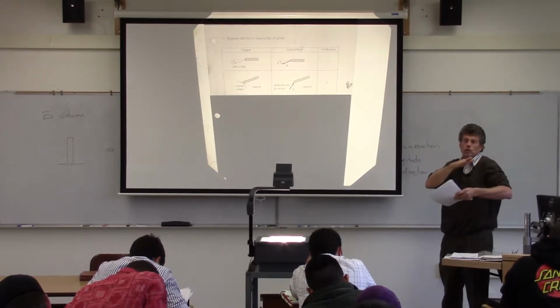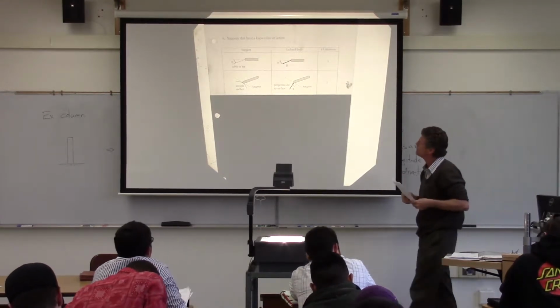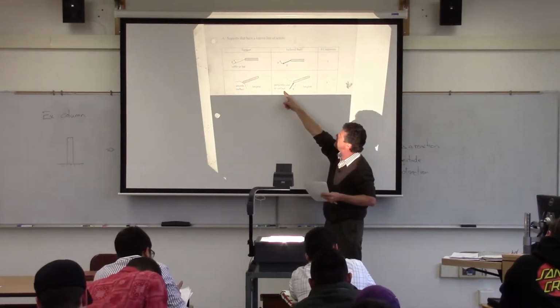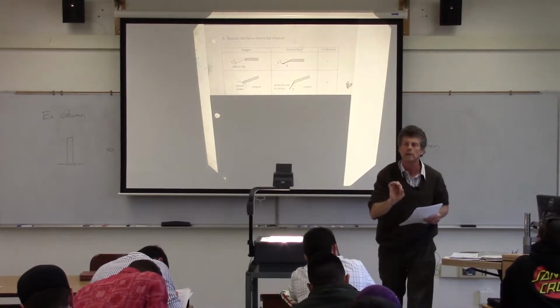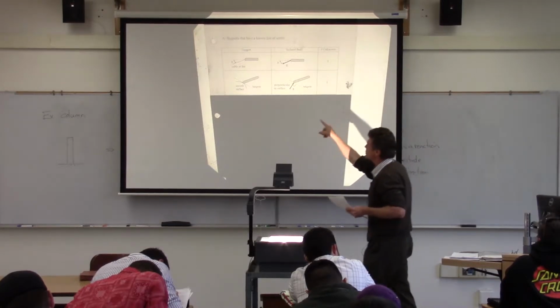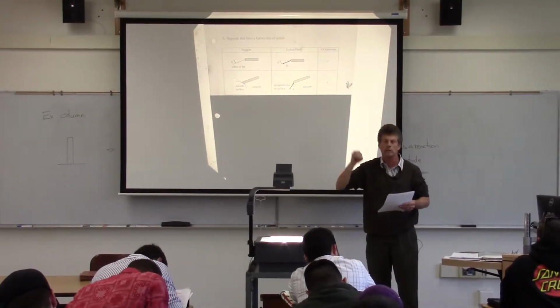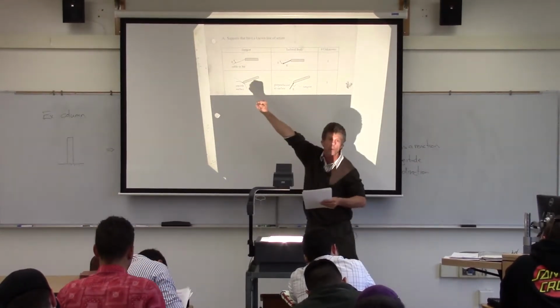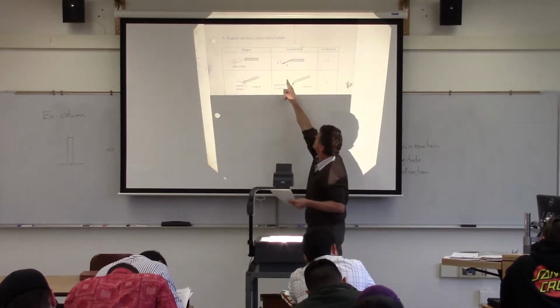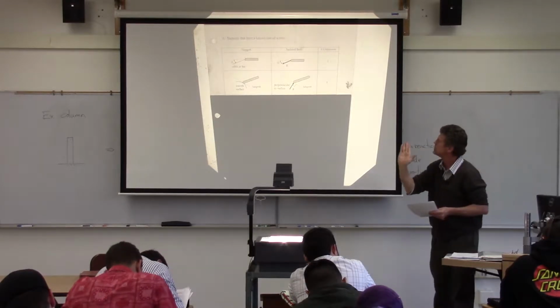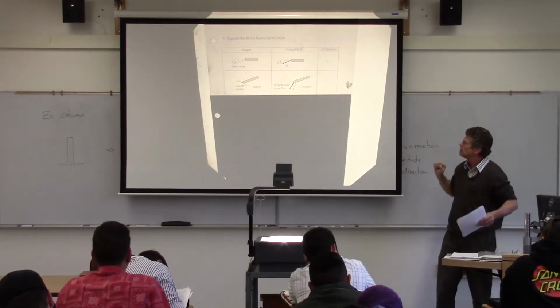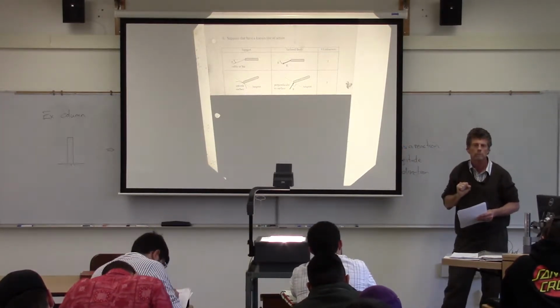Now, if the surface is straight, that's a pretty easy one to figure out. But again, the key thing is that it's perpendicular to the surface, not to the body, okay? Because it's the surface that's saying, no, you're not going to pass through me. Now, if I want to push this way, somewhere along the tangent there, look, there's no force there. That perpendicular force there is not going to restrain me from pushing it along that tangent.